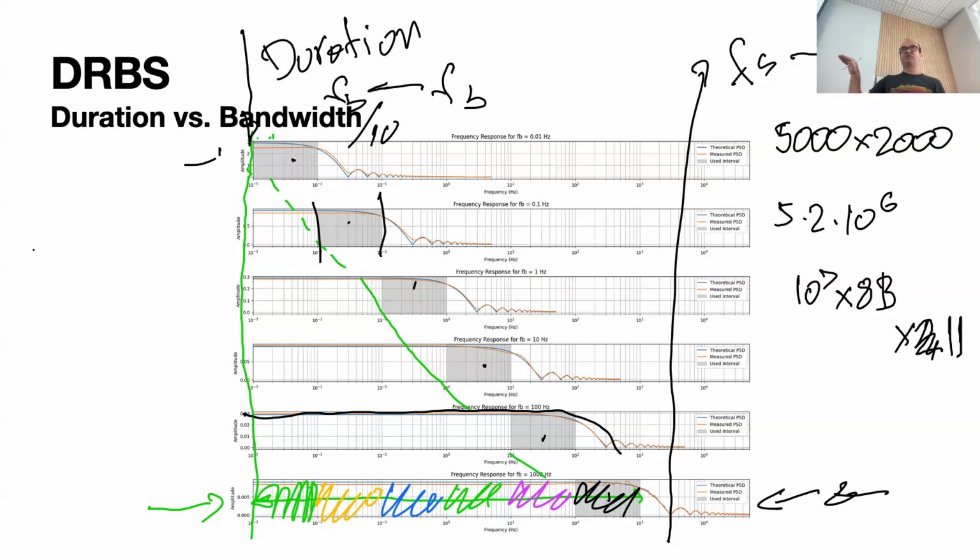On average, they're present. This means that we cannot just take the FFT and calculate everything. We have to slice the signal in time, because at some time points we have excitation and then we don't, and we don't know where these times are. It doesn't mean that when it goes up we have to sample, and when it goes down we don't. These things are not the same.